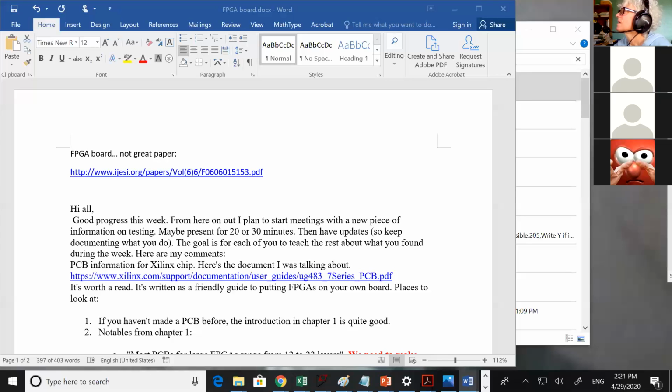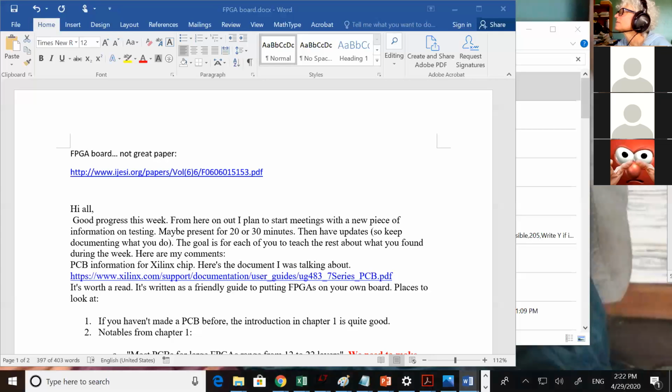A lot of these have an infinite number of solutions. So if you get a little different answer, but it still gives you an Rin greater than 90K and an R out less than 50 ohms, then it's a great solution.